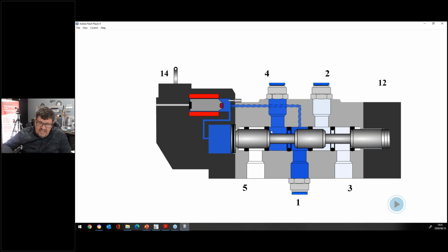also important for the future, if you come and attend any of our courses, remember that the labeling for your solenoid valve is currently 14. Now we start off with 1, 2, 3, 4, 5. And why now suddenly some of 14 and 12? It is because of the airflow through it. That means the airflow from 1 to 4. That's why when you energize this, 1 to 4,